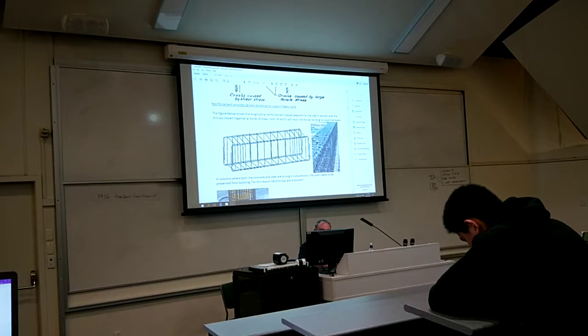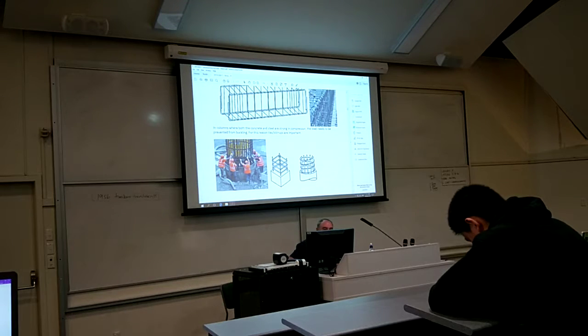If any of you were watching the motorway structures over here at Waterview, a couple of years ago when they were going ahead, you would have noticed this type of reinforcing for the big circular columns. What they tend to do is they will overlap one cage with the previous cage, wire it all up, slide this thing here upwards and do the next pour, and so on and so on. So if you have different pours going on, it's important that a piece of reinforcing goes into that pour with an overlapping piece of reinforcing starting the next pour.